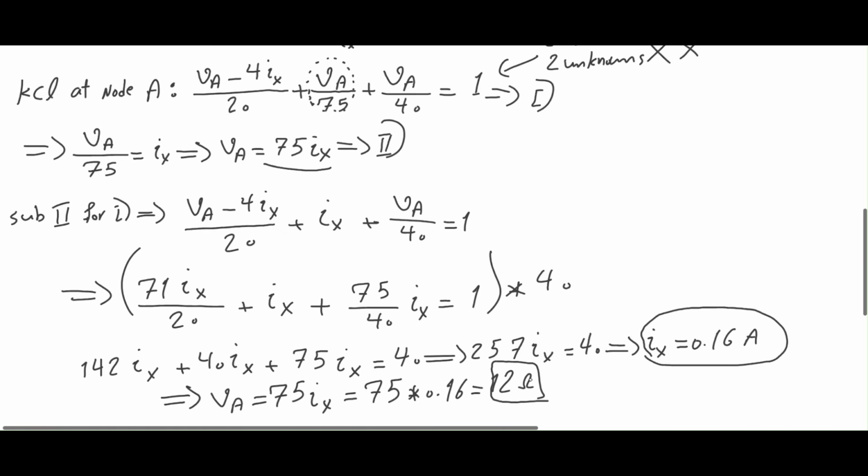I shouldn't have said 12 ohms, it's actually 12 volts. But since we know that R Thevenin is the same as V test, then I can say that my R Thevenin is also 12, but the unit is in ohms. So the Thevenin resistor is 12 ohms.